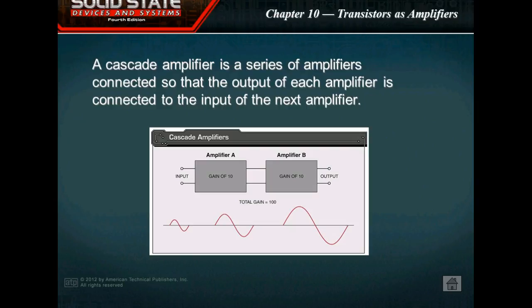So if I knew the two gains, I'd say, okay, I'm putting 5 volts in. I got 2 amplifiers that each have a gain of 3. 3 times 3 is 9. Well, I can take my input and multiply it by 9, which would give me what? 45, right? Y'all understand? So gains multiply.